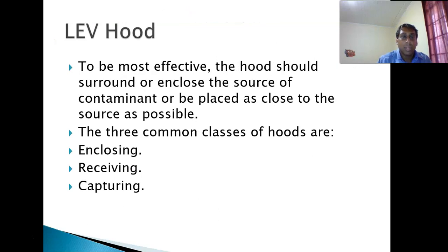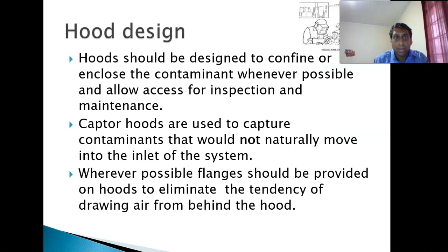Right. So to be most effective, the hood should surround or enclose the source of contaminant, or be placed as close to the source as possible. The three common classes of hoods are enclosing, receiving, capturing. Hoods should be designed to confine or enclose the contaminant whenever possible, as well as allow for inspection and maintenance.